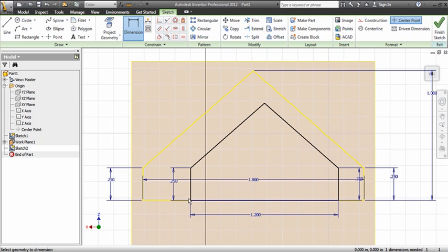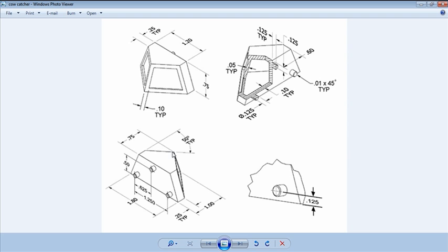And then the final distance we need is the distance from this wall to this wall. Now, in order to find that distance, it's not given to us directly here, but we can figure it out. The total distance here is 1.2, and the total distance here is 1.8. So that's a difference of 0.6. So 0.6 is the difference between this length and this length. So we need to cut 0.6 in half so that it's equally distributed on both sides. So it's going to be 0.3.